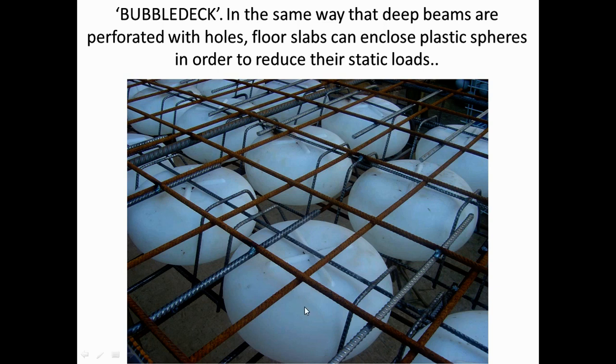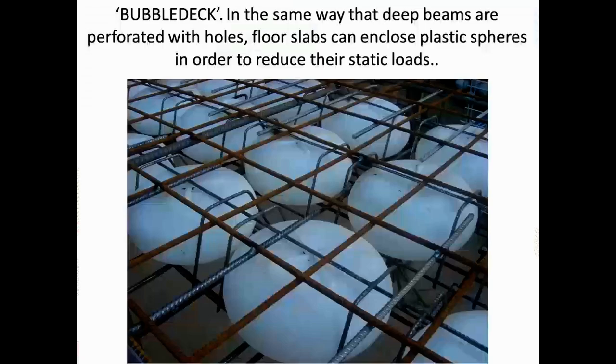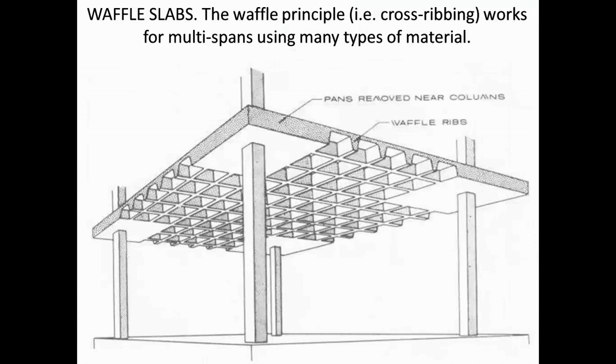That gives us bigger span to depth ratios for the floor. There are still rebars, of course, still steel reinforcing, but as I said, this gives you a much bigger span because the floor is overall a deep section, but it's much lighter than it would have otherwise been. Okay. So this is again a new sort of more common way, and let's face it, we do have to minimize the amount of concrete that we're using in structures, so this is another way to help you do that. Funnily enough, when you draw a section through it, it would look a little bit like a perforated beam, wouldn't it? If you understand.